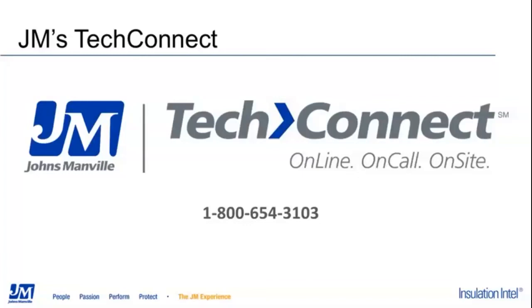All right, thank you. The next one is, Cassie, I'm going to give this one to you. We recently learned about something called a flash bat, which is a combination of spray foam and unfaced bat insulation. What are your thoughts on that in lieu of using a thicker system like what was discussed today? I would say that Johns Manville is an excellent resource for helping you design a hybrid system. This is something that we have done in the past in order to achieve high R values. I don't really think that the term flash is correct because that can be used as a 1/4 inch of spray foam or less.